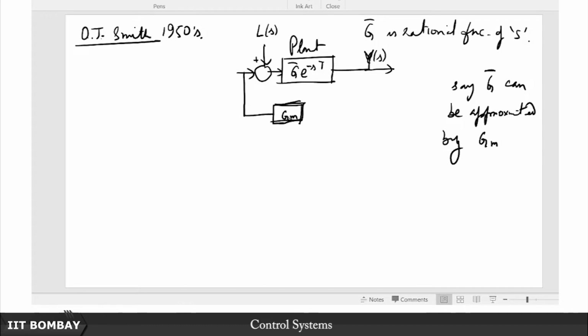So in the actual plant, although it cannot be isolated, in the code it can be isolated. So that's Gm put in here, all right, and I can have a tap in point here, okay, a pick off point here, and I can then write a code for a pure delay e to the minus sT bar, and T bar is an estimate of T. Okay. So based on how well I know this model, how well I have understood this model, how accurately I have captured its behavior, I will be able to get a model for the delay free part of this, which is G bar, and also for the pure time delay, which is e to the minus sT.